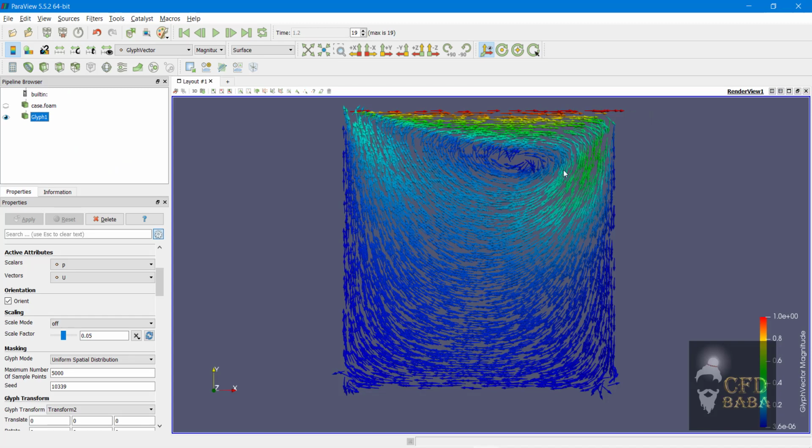One of the interesting properties of fluid is that it tries to stick to any wall surface that it can find. The fluid which is adjacent to the wall surface tries to stick to the wall surface, and when the wall moves, the fluid adjacent to the wall moves along with it. But it cannot go outside our boundaries of fixed walls. That's why it tries to come back into the domain, and thus this sets up a recirculation zone inside our fluid domain. This is the result for time at 1.2 seconds.